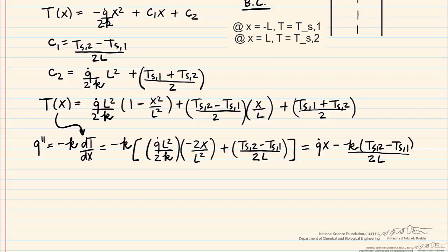What's interesting about this is that here the heat flux is a function of x, unlike one-dimensional steady-state conduction without generation, where the heat flux is independent of x.